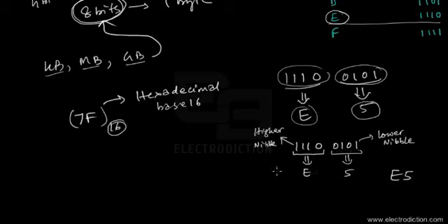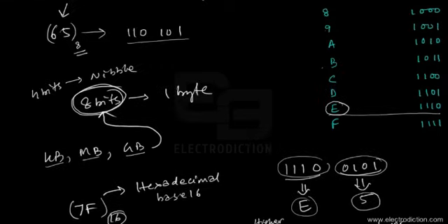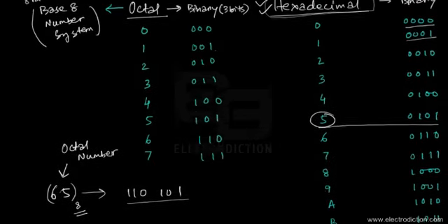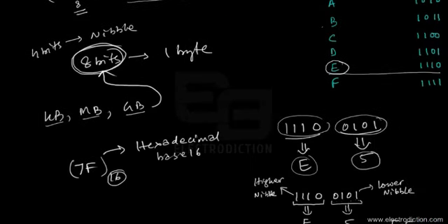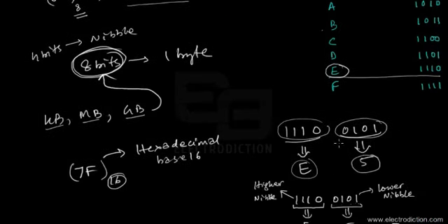In terms of processor systems and digital systems, we write a small h over here, indicating that this number is a hex number, or a hexadecimal number. So that was pretty easy. Given this chart, or if you can just remember the sequence, you can relate any binary number to hexadecimal terminology.